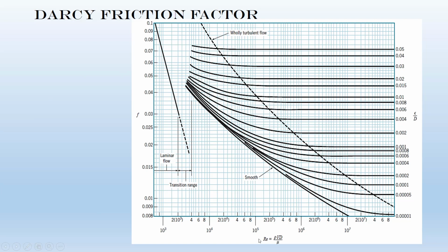Unfortunately, guys, we don't have the Reynolds number. It's unknown. Relative roughness is also unknown, so we have nothing to actually make a decision. However, if you look at this value for the f, I recommend you start from an initial value of 0.02 or 0.025, because you are in the middle of this chart, so this is probably the best one.